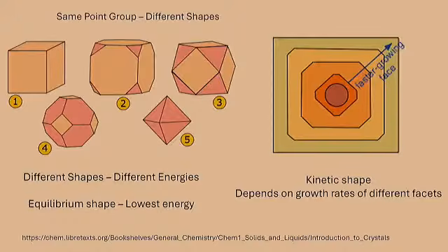What we actually see is what is called the growth morphology. That is basically controlled by kinetics. And here we can explain this in a very simple way. Suppose this is the starting shape of the crystal, which is growing. How does the crystal grow? It basically grows by atom attachment to the existing facets, right? Assume that this facet is growing the fastest. It turns out that finally, after it grows for a significant amount of time, that facet will basically vanish. And what remains in the crystal are the slowest growing facets. The slowest growing facets are what will be left, and therefore, depending upon what is playing a bigger role, the thermodynamics or the kinetics, we can get a very wide range of shapes of these nanoparticles, or whatever we're trying to synthesize, of the crystal in general, right?